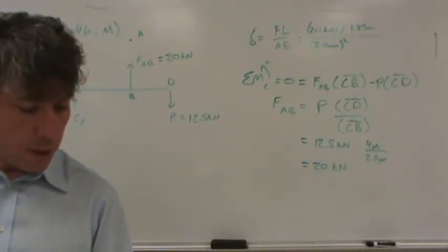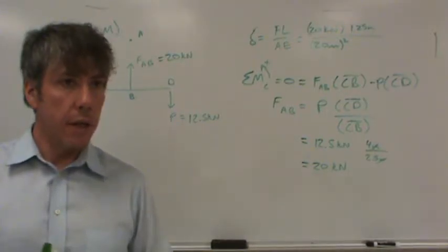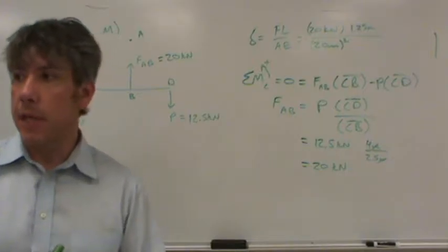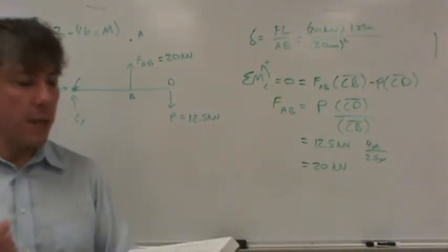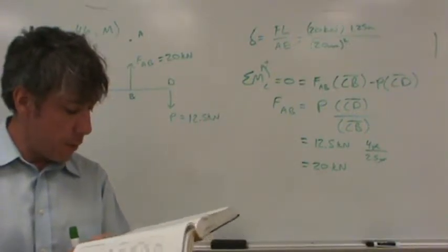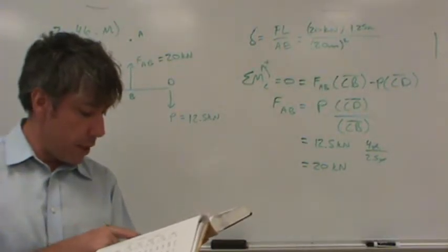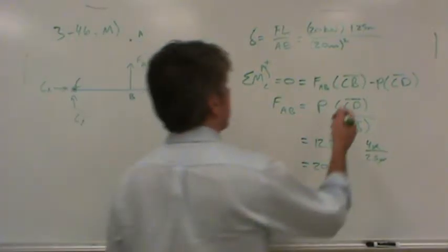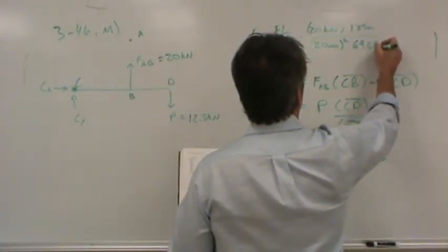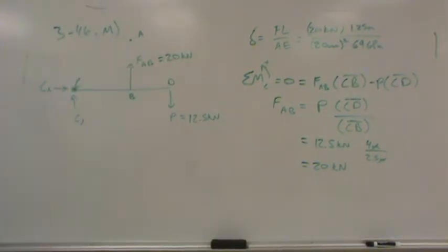Typical properties of aluminum alloys. If you notice, they don't list any elastic moduli. You know why? Because it's a footnote at the bottom of that table. Because the elastic modulus of aluminum really is not sensitive to the alloy and temper. So look at the bottom of the page for the footnote. Elastic modulus for most aluminum alloys, including a bunch of them, is 69 gigapascals. Okay? Does everybody see where I got that from? Okay, questions? We're doing okay?